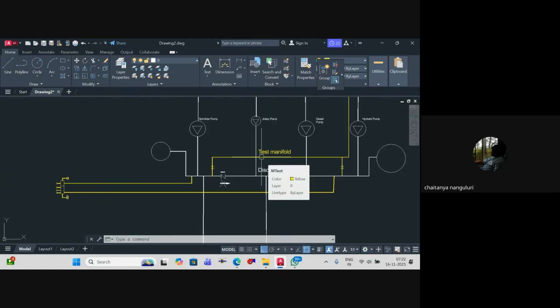At certain times that will drop, sir. Why will it drop unless there's a leakage? If it drops without leakage, it would be because of the temperature, and there's not much impact. Then at max, your booster pump will run again for some time, and again it will be off automatically. It will fulfill the pressure again. Your jockey pump is anyway there to do that activity.